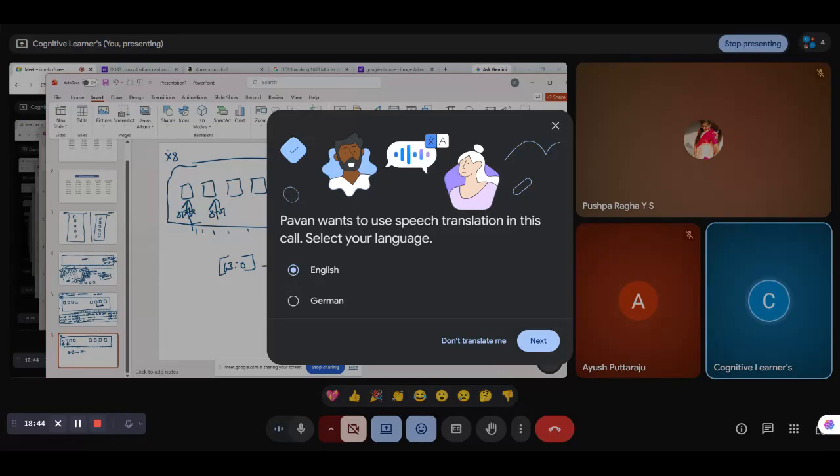Let us assume these are chip 0, chip 1, chip 2, chip 3, chip 4, chip 5, chip 6, chip 7. The 7 down to 0 pins are connected to chip 0, which is 8 bits of data. In the same way, 15 down to 8 is connected to chip 1, again 8 bits.